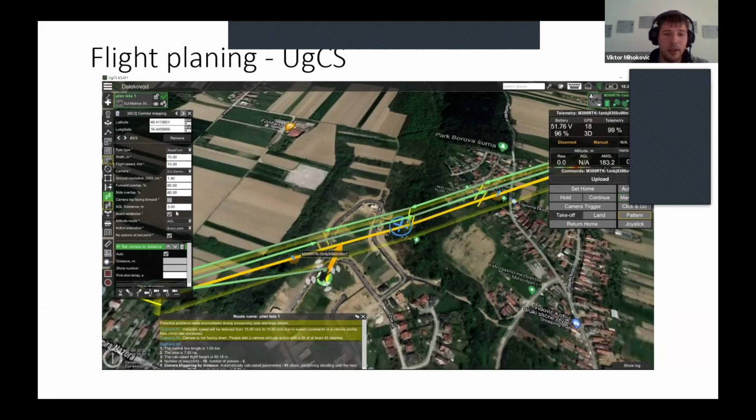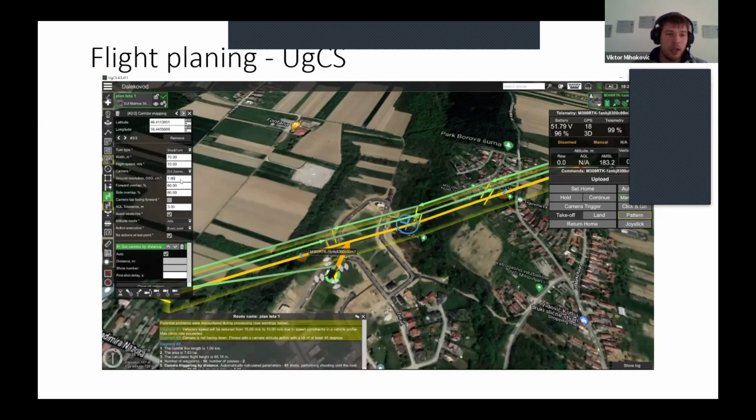It's very fast, but from our experience this is the speed from which you can get enough data, and you can also maximize the flight time of your batteries. But it is important to say that if the conditions outside are cold, if it's below zero, you should maybe go with a flight speed of 5 meters per second, just to be safe because of your drone.